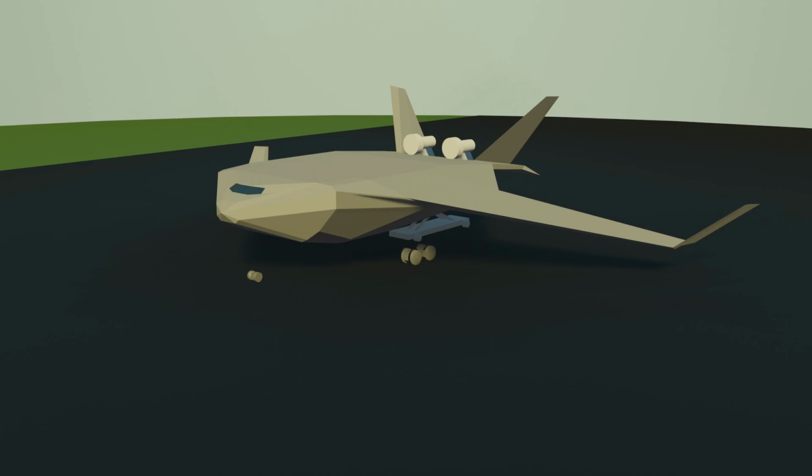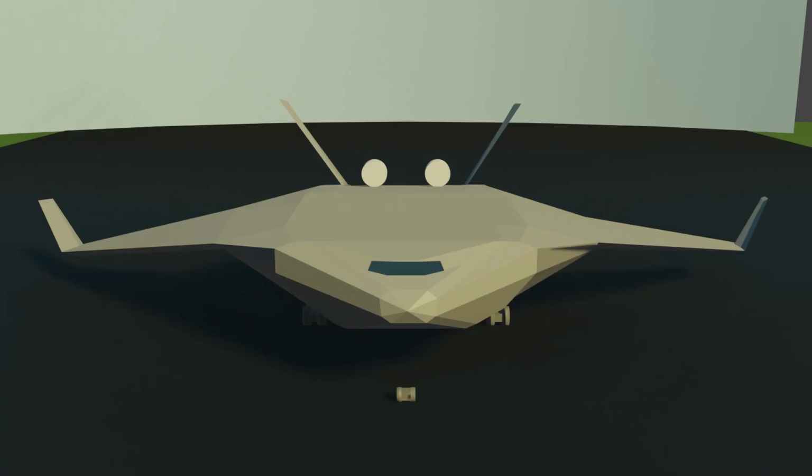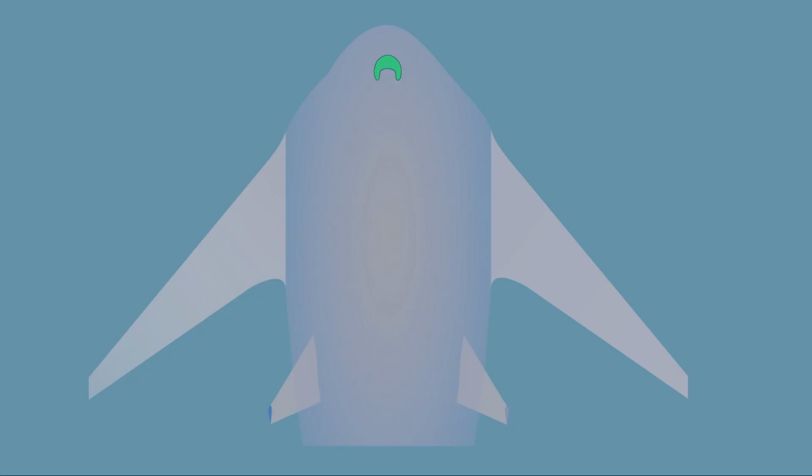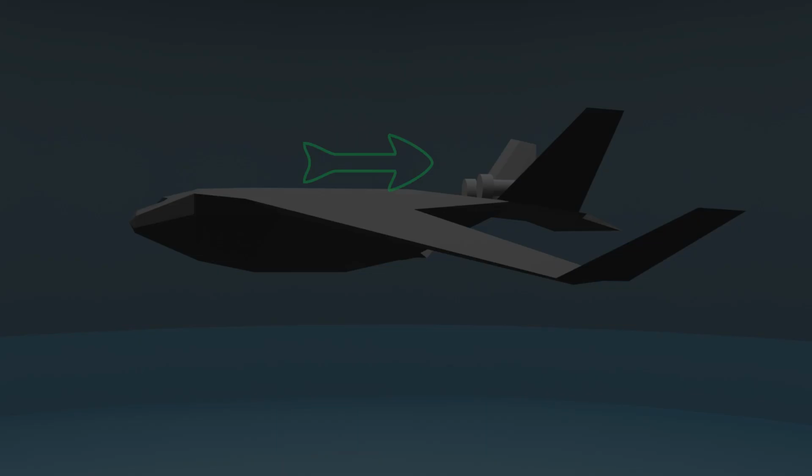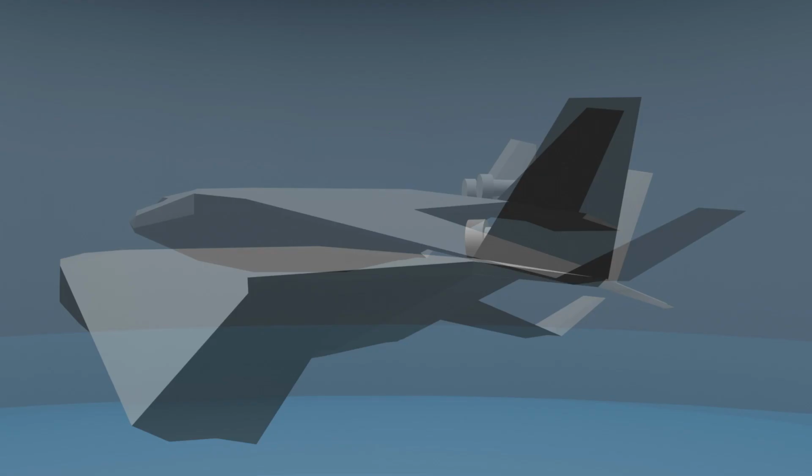Since the 1980s, work has been done on blended wing-body aircraft. That is an aircraft with a relatively square central fuselage instead of the usual cylindrical fuselage. The main reason for doing this is to reduce the wetted surface, the total external surface of the aircraft. In a commercial airliner, roughly 50% of the drag is from skin friction drag. That is the air physically being scraped over the fuselage of the aircraft. If the area is reduced, then the total drag is reduced.